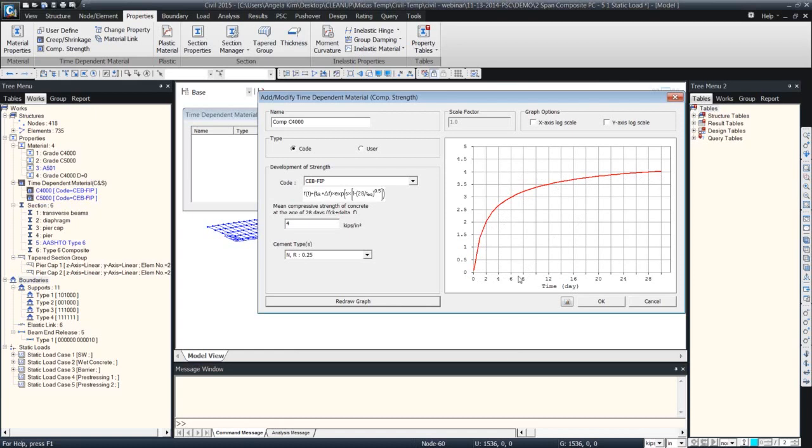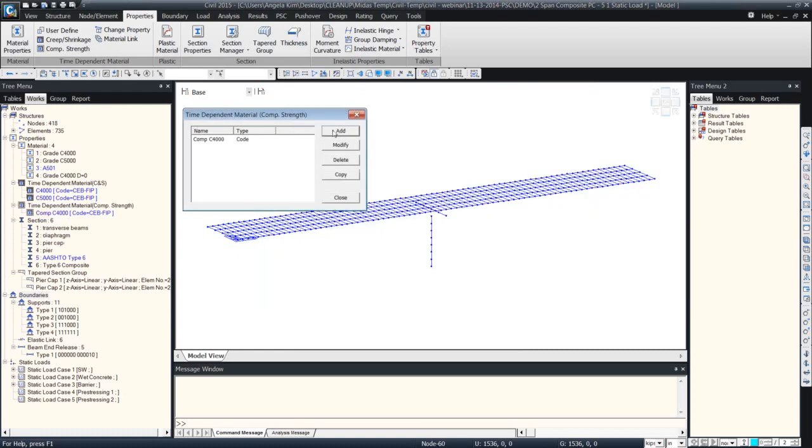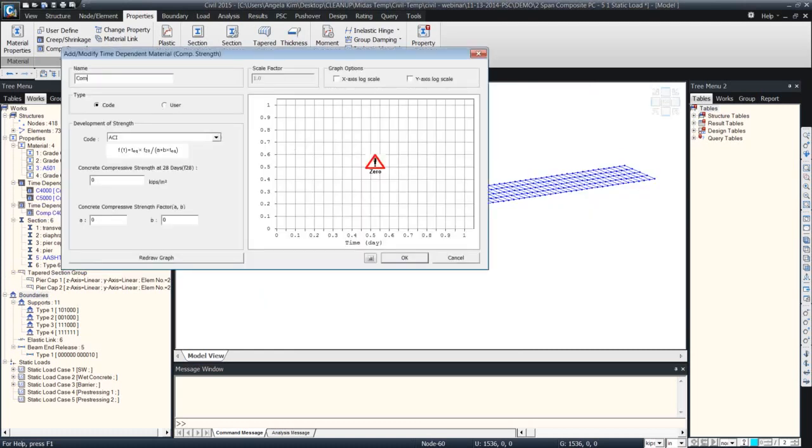And let's say I need to activate the beam, the girder, with the stiffness of, let's say, 6 days with 3 KSI. Then you can define your age to be 6, so that the element, when it's activated, carries the stiffness at the day of 6. So basically, you can reflect the actual construction, the false work application, and so on. Going to do the same for the girder.